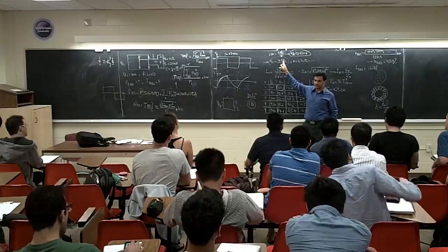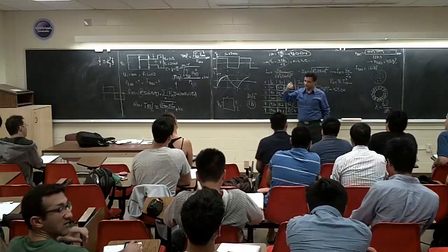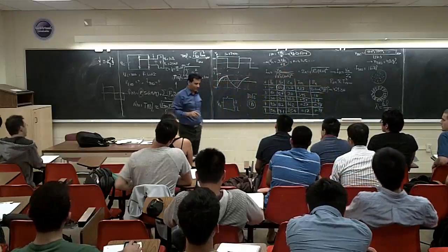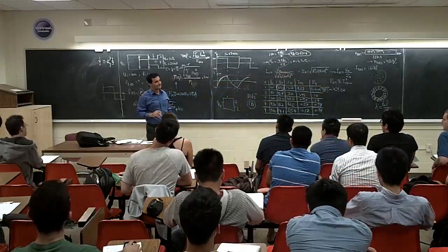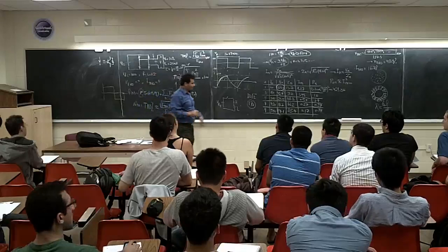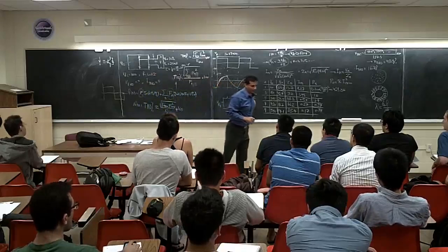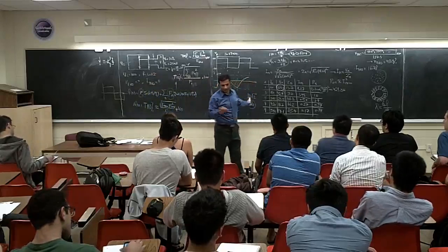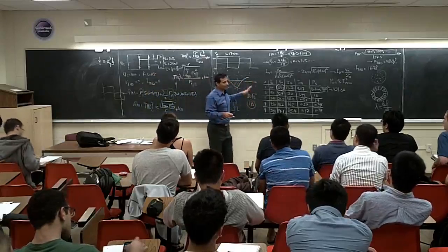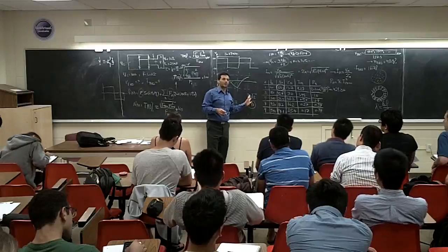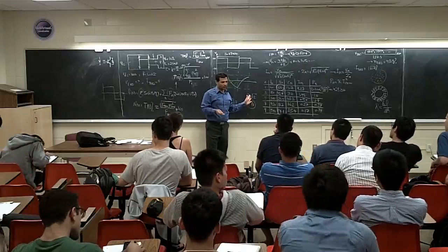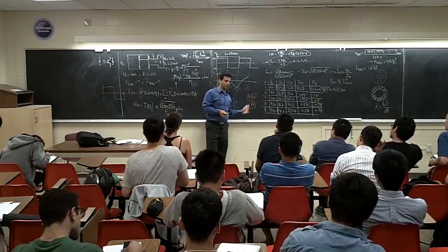You select this one and you go a little bit higher, not a lot. If you go a lot higher, what's going to happen? Instead of having 110, maybe you have 140 volt, and that way you're going to kill your equipment. If you design it for 120 it's good, because usually when they say 110, those equipment can easily work with 120 or 105.